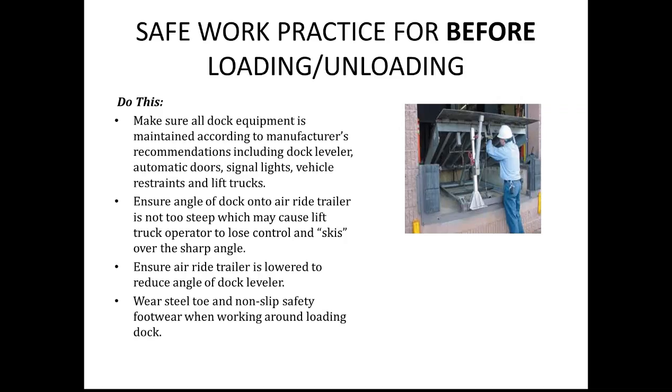The thing to remember is that anybody working on a dock leveler or loading dock must wear steel toed shoes and non-slip footwear. One thing I want to point out is in that picture, you'll see what they call a toe guard, which is a flange on the edge that, see if I can point to it right there. So that protects a toe from getting caught as the plate comes down.